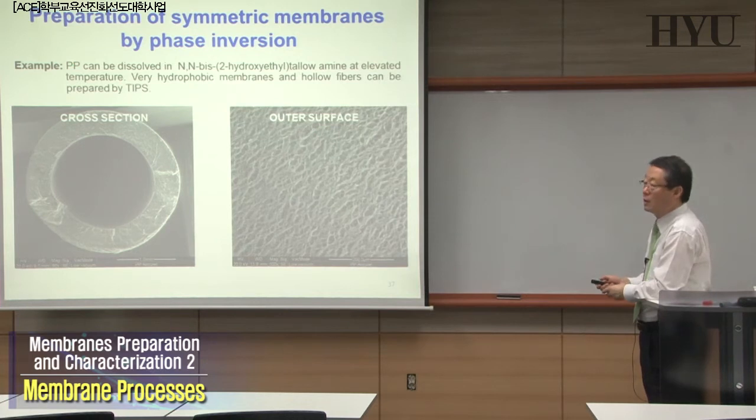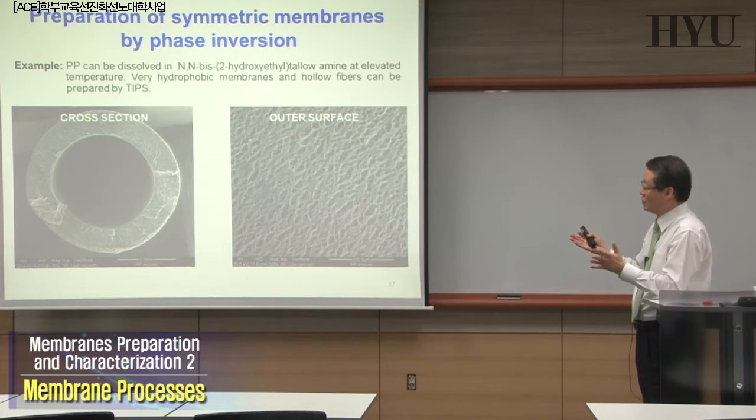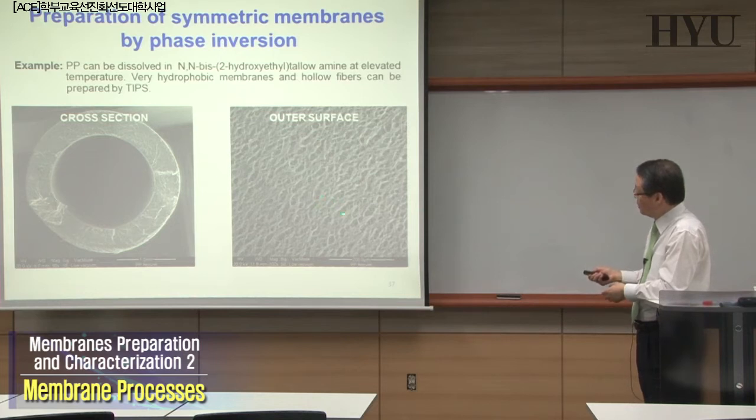Polypropylene is hydrophobic, so polypropylene hollow fiber is very useful in some applications. Mitsubishi Rayon is making this polyethylene and polypropylene hollow fiber for microfiltration purposes and MBR, membrane bioreactor systems, and this is one of the examples. In the meantime, polypropylene could be fabricated into a flat sheet by Celanese, and they could make a Celgard membrane with pore structures like this. Okay? Of course, pore structure might be a little different depending upon the manufacturing process. You see the micropores on the surface of the membrane, and you still have micropores, although they are not seen in here.